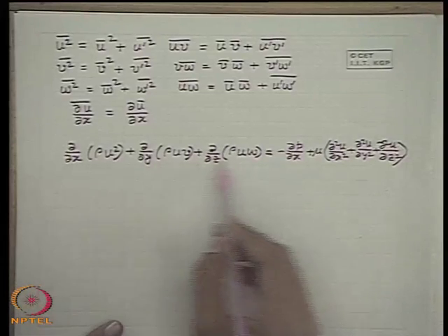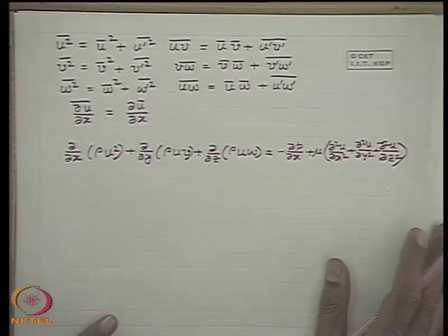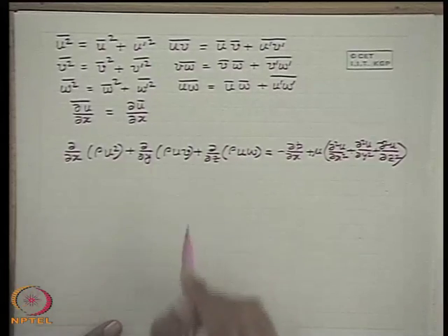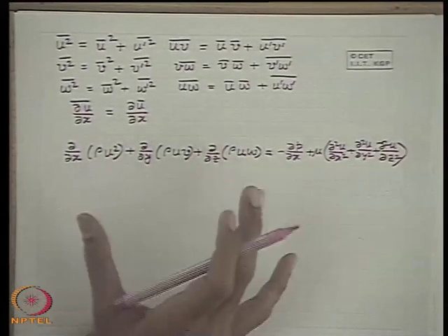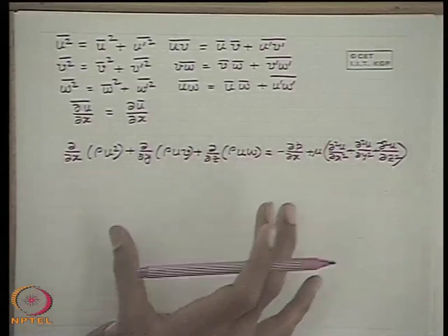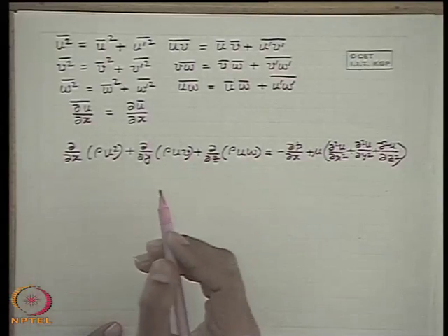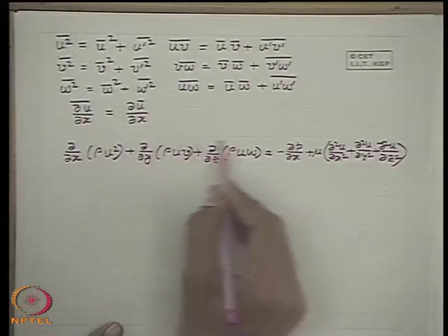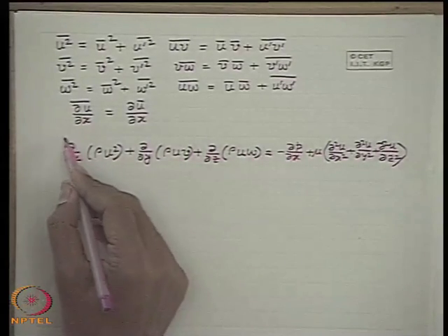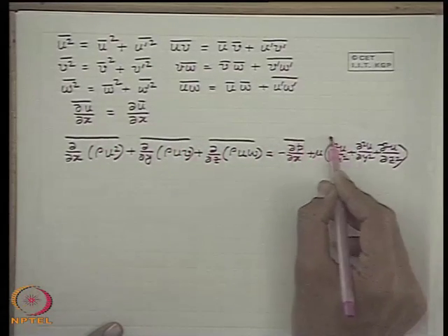So with all these rules, now let us look at how you do the modifications for the Navier-Stokes equation. Let us see the x direction Navier-Stokes equation in the conservative form, which we have just derived. And the first step is that we take the time average quantities of this Navier-Stokes equation. That means physically we try to express the equation of motion on a time average basis. That means we take the time average for both the left hand and right hand side, term by term.